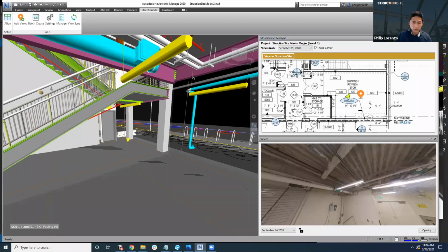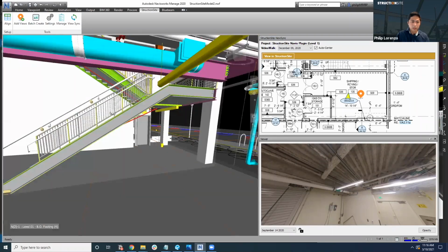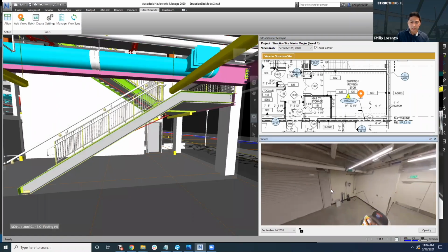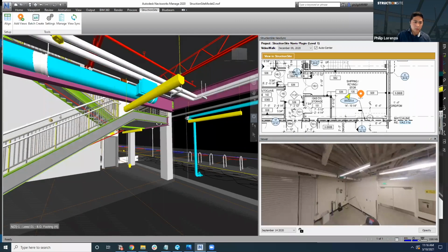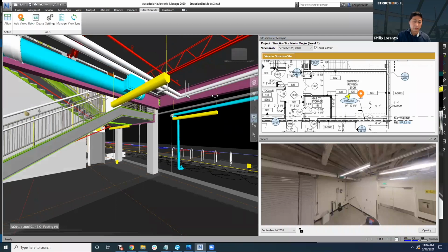We think it might be even better. And just in terms of the controls, there are some small questions there. You can control these independently, and then if you hit lock, it will sync the views. No matter where you move in the model, and if you're using, say, a 3D mouse, something like that, it'll track it automatically over here. Notice that the floor plan is only in 2D though, so it won't necessarily track your elevations. If you want to track a different level, then you'll have to go in and pull up a different level of the model, which will have its own alignment saved.